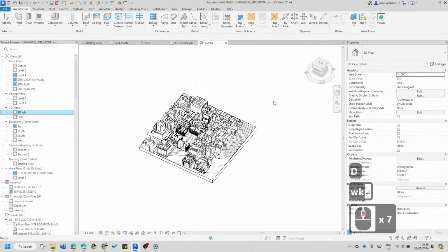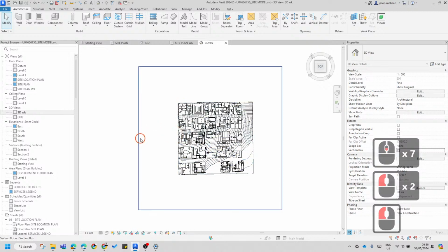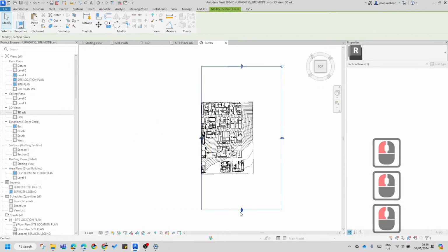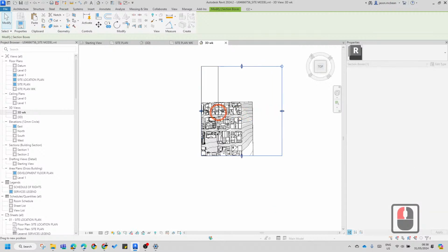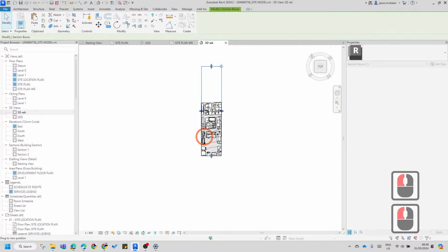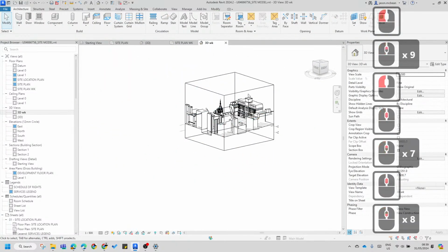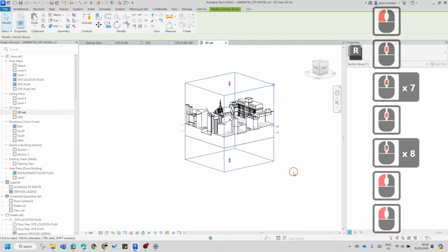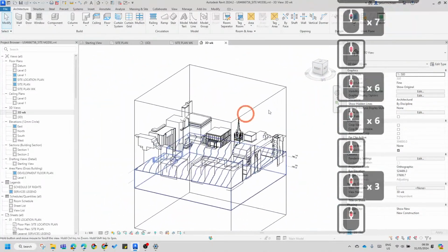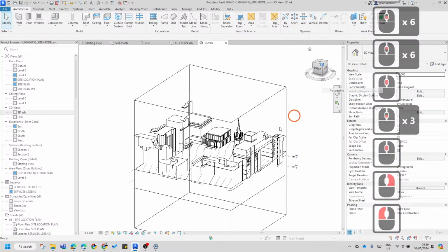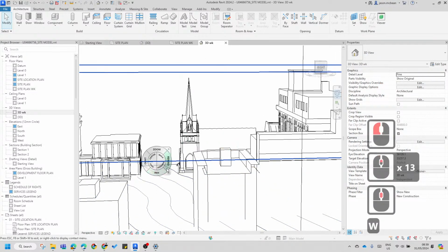In this view I'm going to switch on a section box and focus on a very specific area. You can have multiple 3D views for different purposes, because there's too much other data to work with from time to time, which gets quite annoying. That's all I want to work with. Sometimes I like to switch to perspective, so when I'm zooming in, with Shift W, I can walk around a bit.